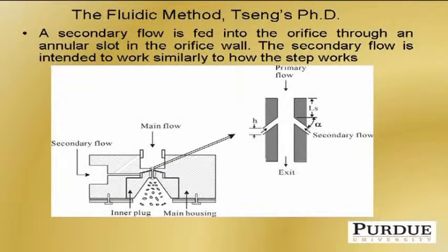So we thought, well, how can liquid injection do that? And the answer is to have the liquid come in and get turned downstream. That process of turning the streamline downstream needs higher pressure above it than below. And so maybe if we inject liquid upwards like this, that for it to be turned and flow down out the exit will create a similar pressure field as the step. And so we built a transparent system here, kind of a cylindrical plenum with a conical injection slot.